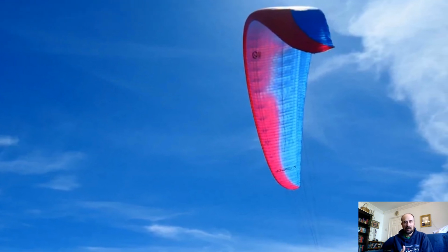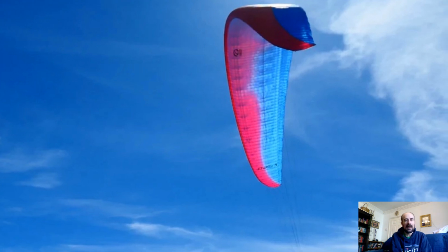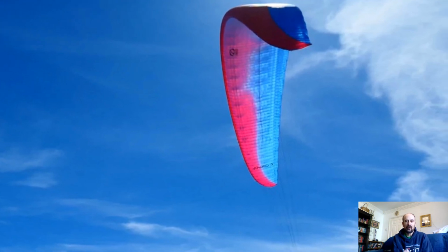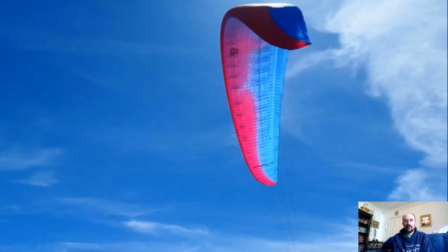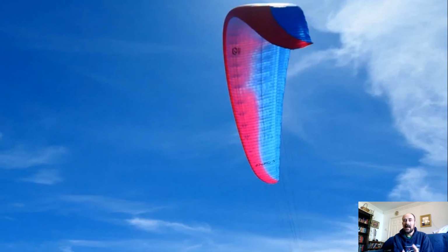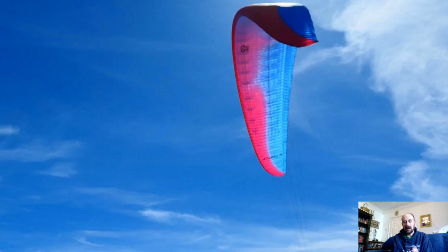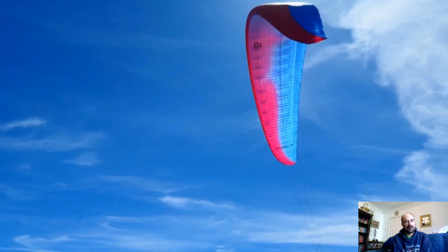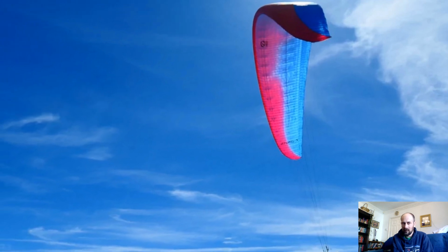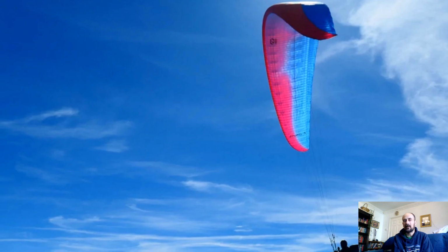Then you've got the inevitable drag of the lines. You've got the vents in the leading edge as well, so you've got a lot of sources of parasitic drag which you just can't get rid of on a paraglider. So they really shouldn't be getting anywhere close to a hang glider. And yet they really are. Especially the highest of the high performance ones are now snapping at the heels of hang gliders for max glide at least, and better for min sink rate.